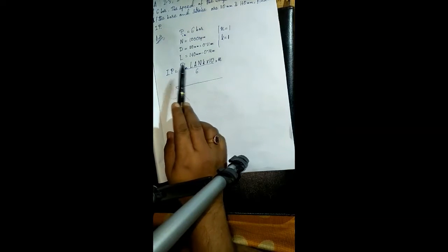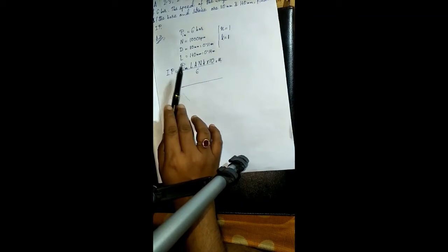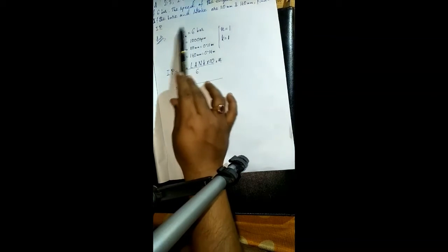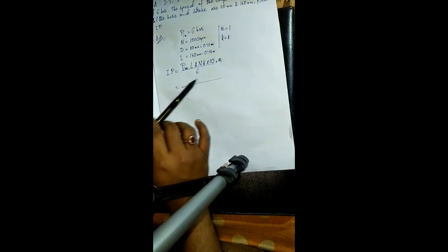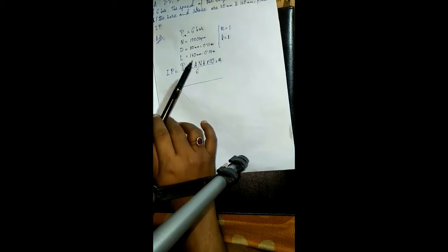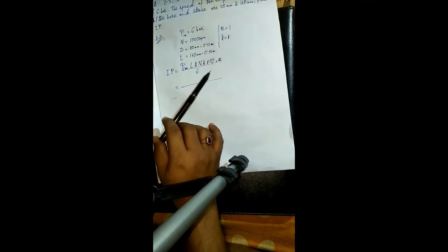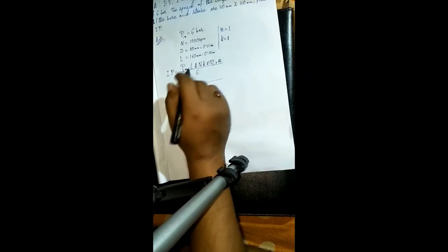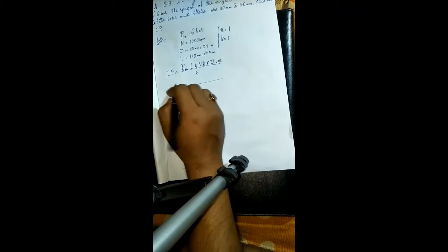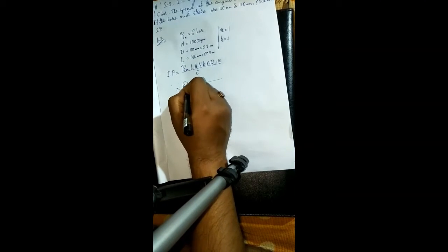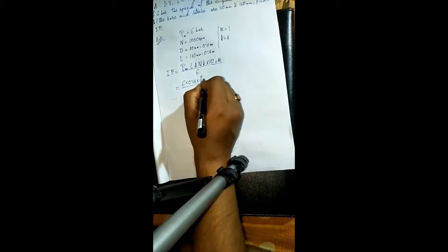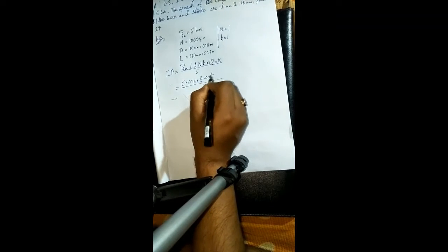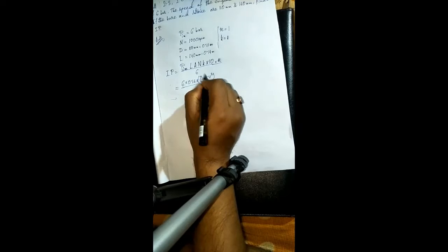Okay, one thing, in this expression for the value of P, don't convert the pressure into Pascal or Newton per meter square, because in this expression the bar is already converted into Pascal. So you don't need to convert that pressure in bar into Pascal. Now just substituting all these values: 6 into 0.14 into pi by 4 D square, this is the piston area.